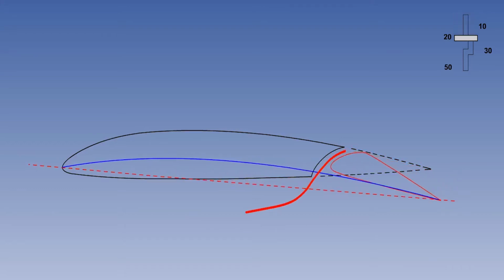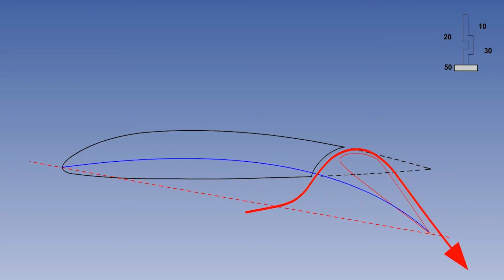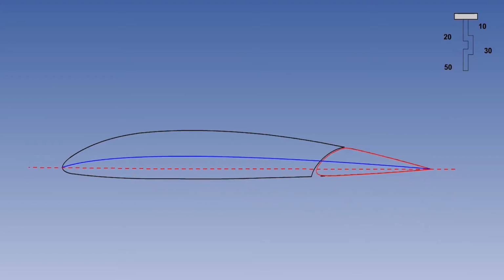When the slotted flap is lowered, a slot is opened between the leading edge of the flap and the trailing edge of the wing. The slot directs high-energy airflow from the bottom surface of the wing onto the upper surface of the flap. This increases the kinetic energy in the boundary layer over the flap. Therefore, the slotted flap can be lowered to a larger angle before airflow separation begins. This allows a greater increase in CLmax with much less drag than is possible with either the plain or the split flap. A slotted flap can have more than one slot.